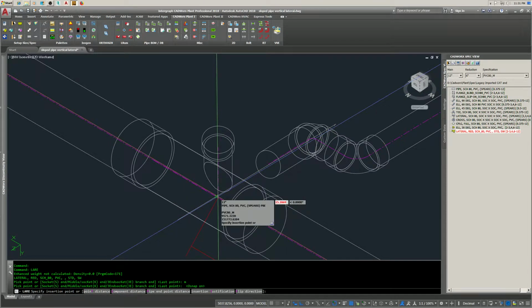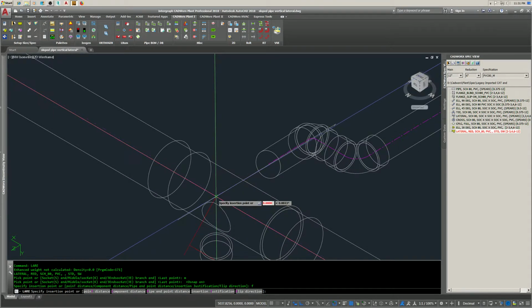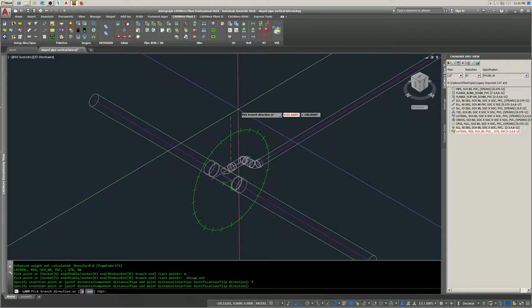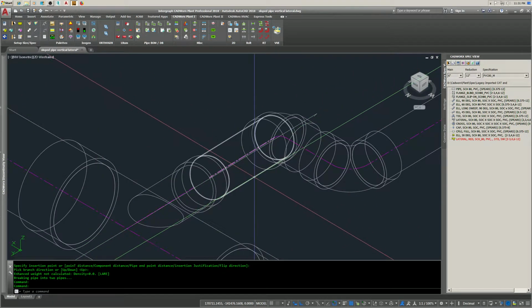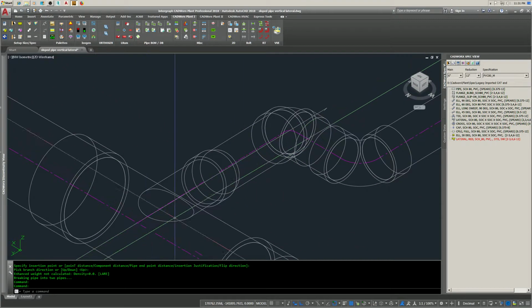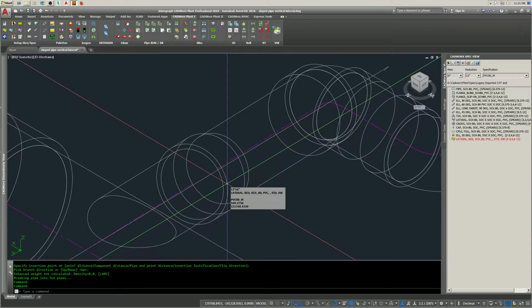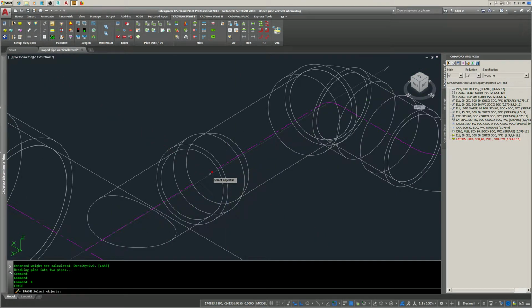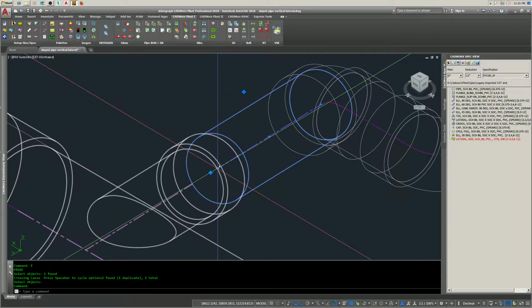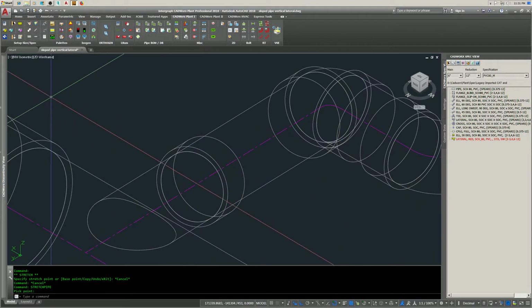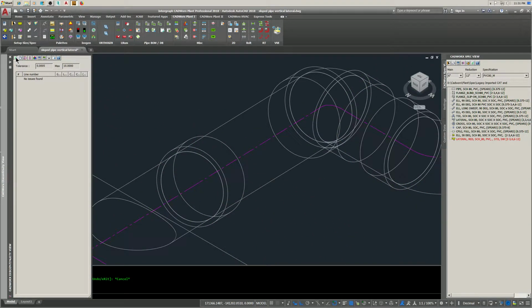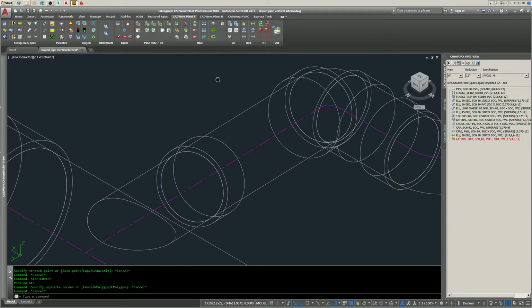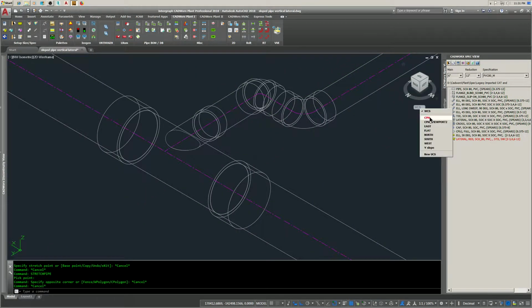You can see we're going the wrong way with that. We'll use the flip direction function. Put it in straight up. The reason I pull this up, when you insert this lateral, sometimes it'll pick up on that end point and the lateral comes in all cockeyed. Now we can erase our construction lines. And we can tie this into our lateral. We'll check our continuity and we're good. Back to the world.